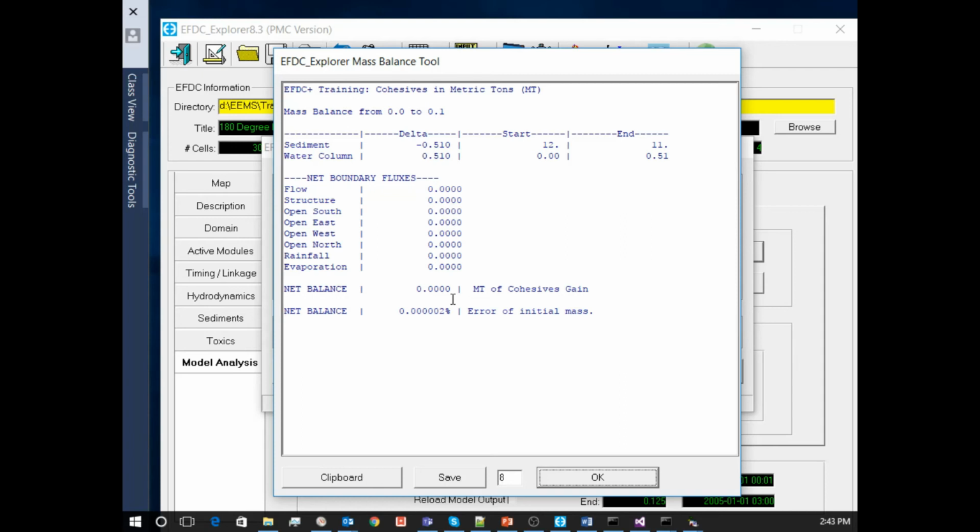That's a decision that the modeler will have to make, and then decide, am I going to put this in as a groundwater source, or just as a killer decision, because the HSPF model drained the reservoir. So they had to have makeup water, and they bring it in at a series of different tribs that they're calling local runoff, to account for the water balance difference. That's how they made it up.